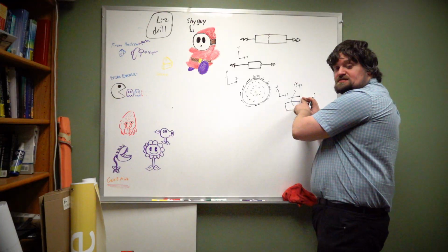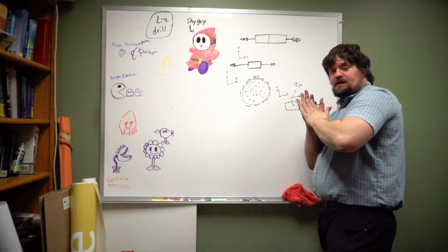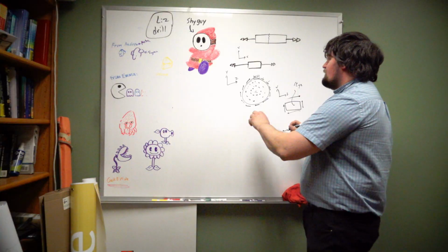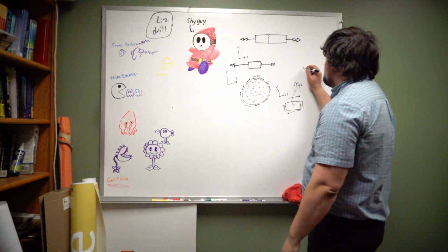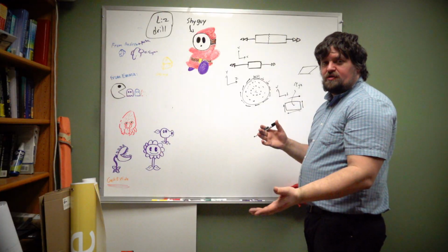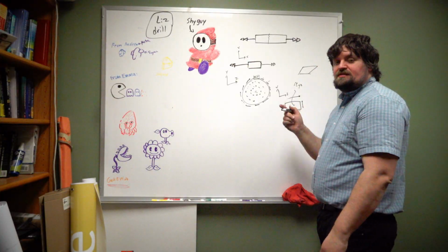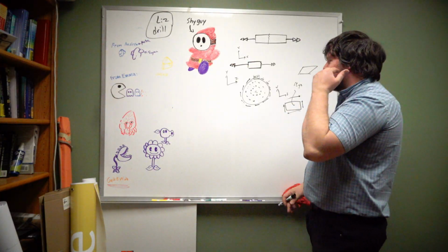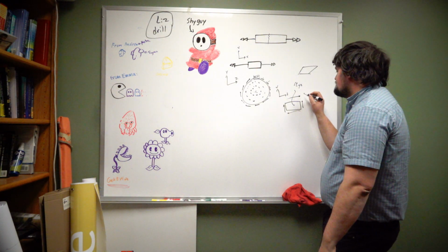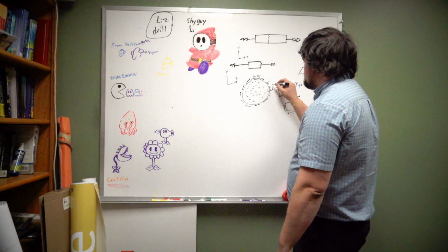We also know that since this is a shear load, a shear stress, because it is parallel to the face it's acting on, we're also going to have additional shear stresses that arise in all of these. And what that's going to do is it's going to cause the element to twist in that way, which is actually where we get the iconic twisting of a torsionally loaded member. All of the unit cells look like this. So we have tau YZ here, tau YZ here, tau YZ here, tau YZ here. Okay. Now let's go ahead and look at this one down here.